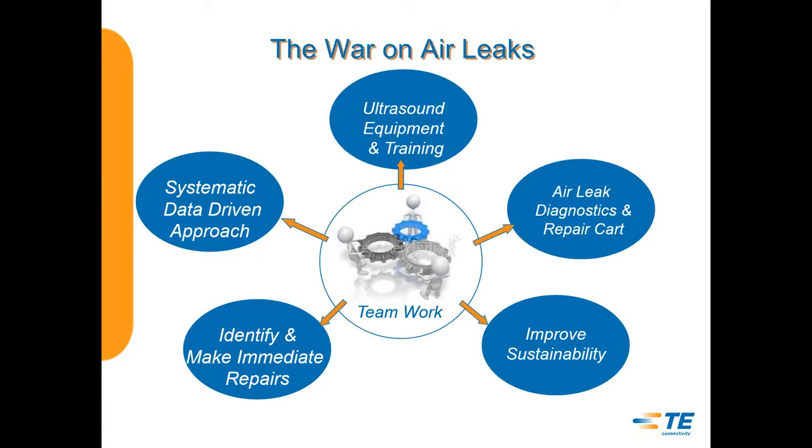And we saw a lot of Teflon tape being used, which is against our preference. We like to use the pipe dope. It doesn't break loose and get in the valves and things and clog it up. So there's just a lot of opportunity there to improve the sustainability of it.